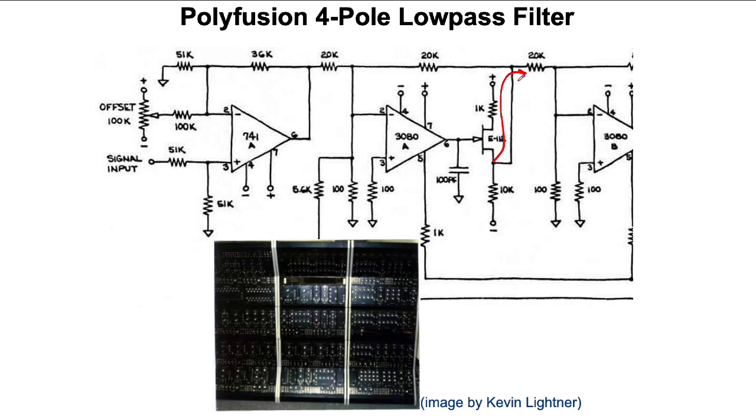Anyway, the output here is being presented to the next stage, but it's also being fed back through this 20K resistor, and that's part of this RC where we replace the resistor with an OTA kind of structure. And so we can deal with this with a fairly simple formula because my R big going forward here and going backwards are the same. So I can take that 1/200 attenuation factor from the resistor divider, both directions, and just lump it into the gain of the OTA. Another assumption I should mention that I'm making here is that whatever else is happening down here, this 5.6K is so big compared to this 100K that when figuring out what's happening with this voltage divider, I can just ignore what's happening here and treat it as equivalent to the next stage with the 100 ohm here and so on and so forth.